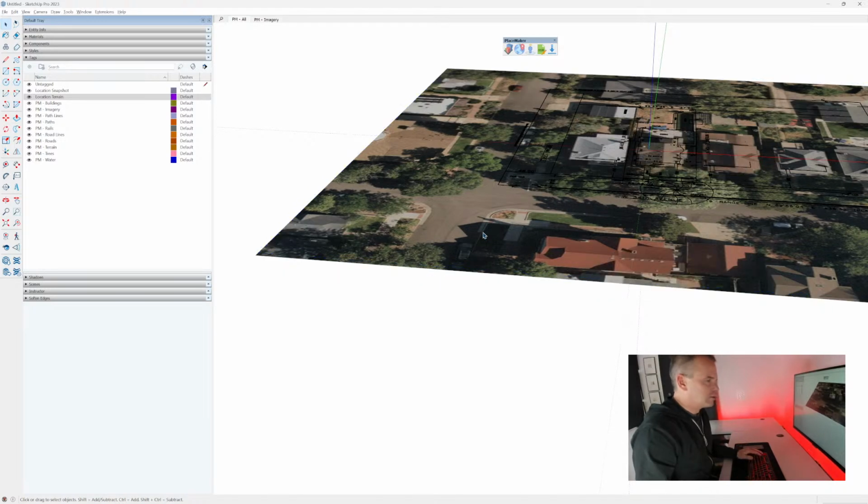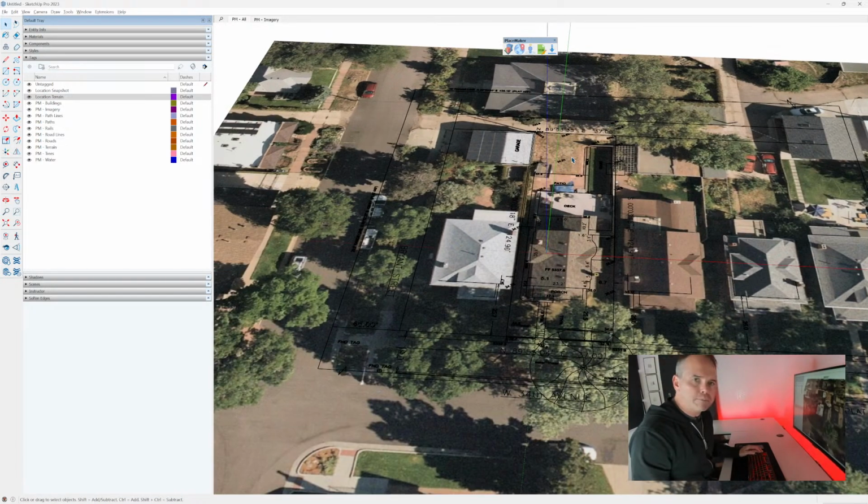I don't want to mess with just a subtle terrain. It's a little bit more difficult to work with. And especially with a simple project like this, I'm going to have a very simple, straightforward bulk plane, what do they call it? Base plane, where we start in the elevation. So it's really not worth trying to model the site. If this project were on a giant hillside, then totally I would use the terrain.